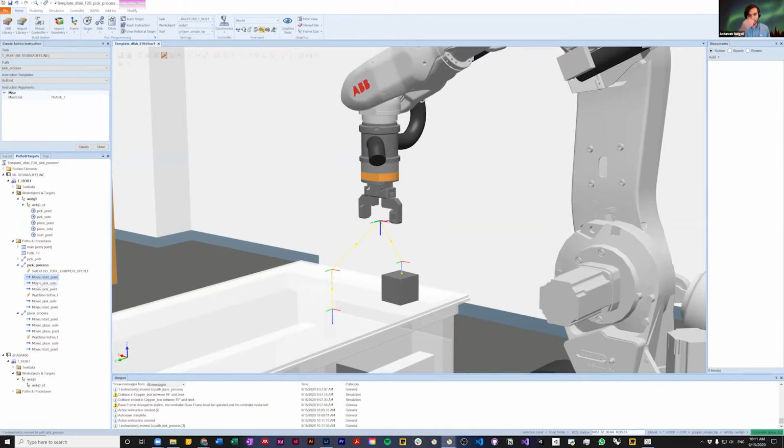Whenever you're doing something with these robots, you should never trust the person who used the robot before you, and you should never trust yourself from 5 minutes ago. So whenever you are starting a process with the robot, make sure that you are resetting everything into its original position. Never assume that the previous person, including yourself or me, has done this job for you. So whenever we are doing the job, we want to make sure that our gripper is open. Just imagine that you want to grab something and you go all the way to the object, and then you realize that, oh, my gripper is closed, so it cannot get any closer. So make sure that your gripper is open at the beginning, then start the workflow.